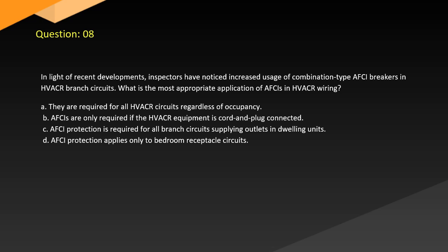A. They are required for all HVACR circuits regardless of occupancy. B. AFCIs are only required if the HVACR equipment is cord and plug connected. C. AFCI protection is required for all branch circuits supplying outlets in dwelling units. D. AFCI protection applies only to bedroom receptacle circuits.